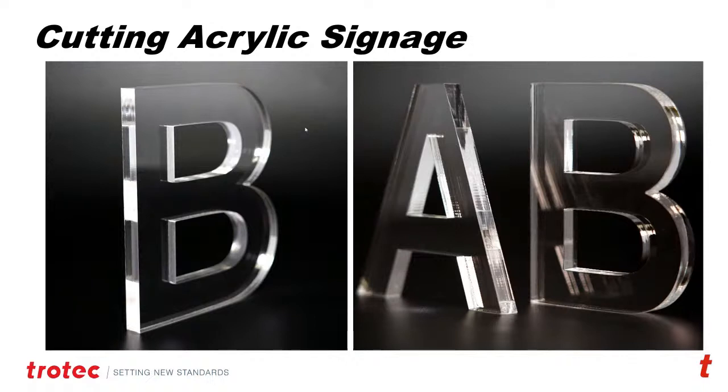But dimensional letters are very popular with the laser system, because dimensional letters will give you the ability to give you that raised physical letter component of signage, which means that laser cutting is ideal for that. The other benefit, unlike routers and other methods of cutting, you can get the real tight corners. The beam diameter on the laser, typical beam is 5/1000ths of an inch in diameter. That means when you're cutting a corner or a star or a shape, you're not limited to like a bit size. In addition to getting that flame polished edge, you can also get that nice tight cut with the laser systems.